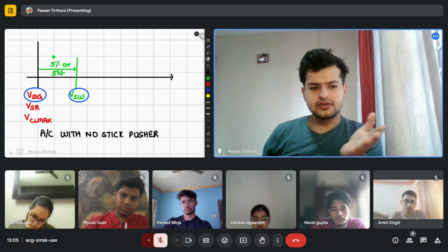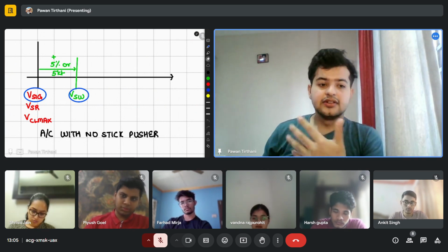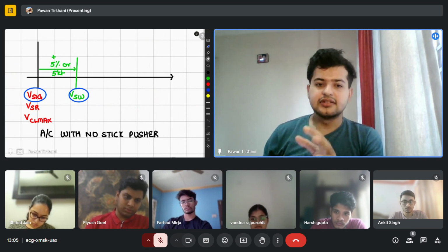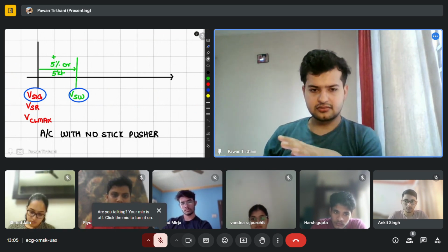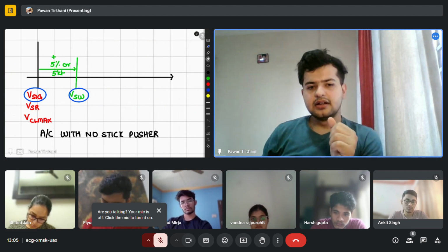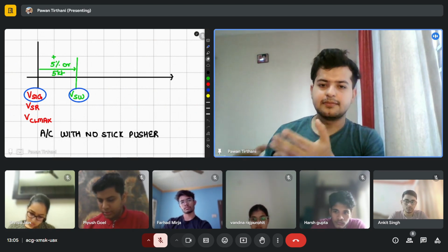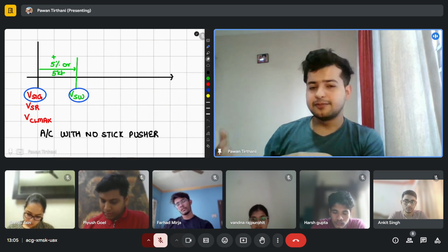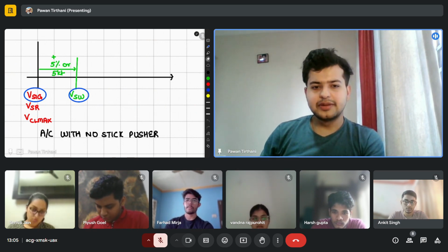So VS1G or the reference stall speed. VS1G small aircrafts के लिए, VSR बड़े aircrafts के लिए. यहाँ in general terms VCL max जो हम लोगों ने last day पढ़ा, उससे 5% ahead आप stall warning की speed रखते हो, या 5 knot. So ये 5% और 5 knots क्यों है? I'll tell you. So let's say your stall speed is 100 knots.